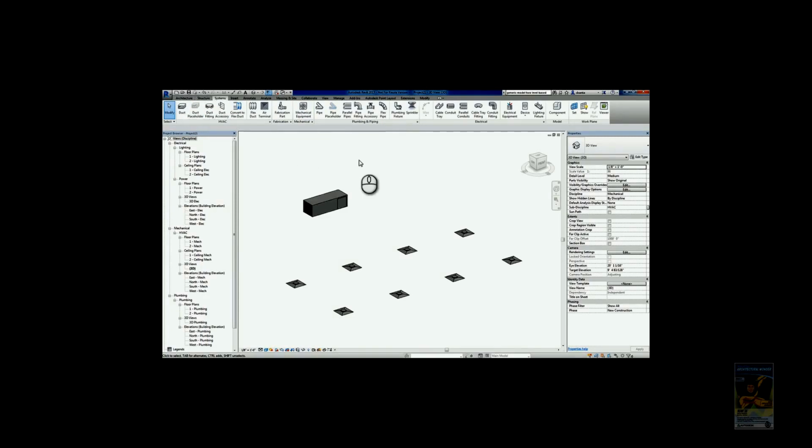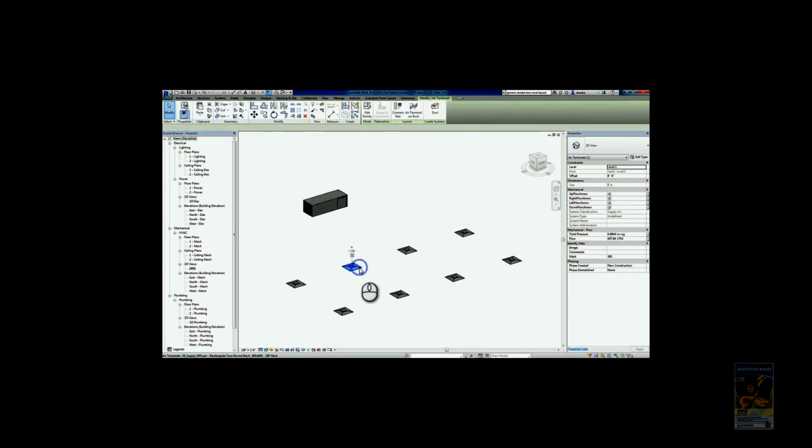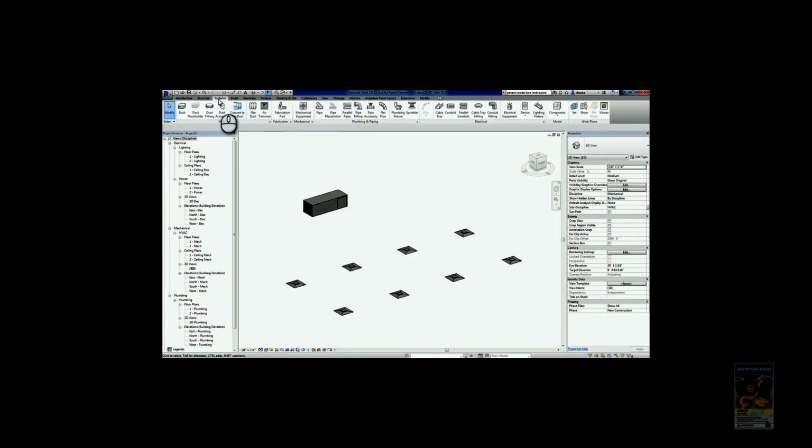Here I am in Autodesk Revit 2017, which contains all 3 flavors of Revit, Architecture, Structure, and Systems. I'm working with a project that is based upon the Systems default template file. And I have some air diffusers and a unit. If we go to the Systems tab of the ribbon, we notice we have a lot of tools here to create manually ducts, duct placeholders, fittings, accessories, converting to flexible duct, so on and so forth.